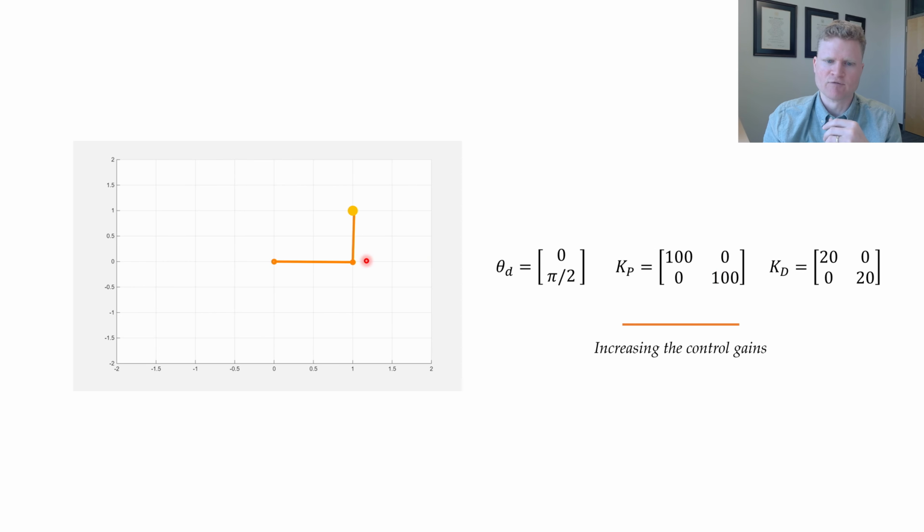And now you can see a video of the robot quickly snapping to that desired joint position. It's not perfect. You can kind of see that it's oscillating. It goes a little bit beyond the desired joint position, then goes backwards. I'd call this an oscillation. So it's not perfect, and you can actually improve this by tuning the gains yourself as part of the practice set, but it's better than what we saw before.